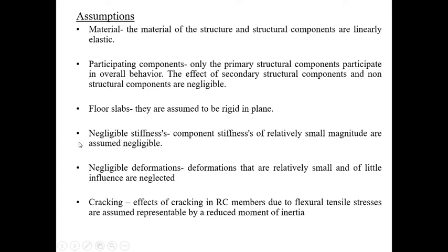Then next is negligible stiffnesses. Whatever the stiffness of the different components, if they have a very small value, they can be assumed to be negligible or they are not considered. The use of this assumption should depend on the role of that component in the structure.